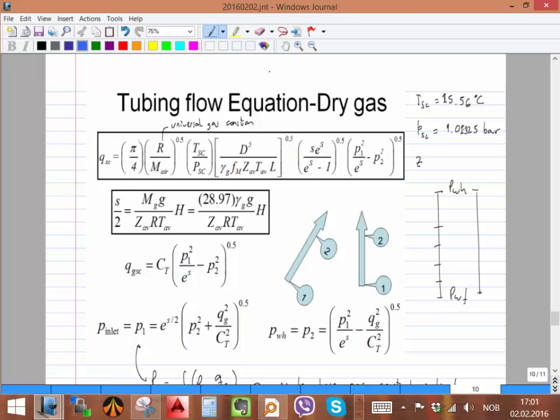And of course, then we're going to say what happens when there are changes with time. Okay, we're going to introduce some time changes, and we will do that not with a reservoir simulator, but with material balance. Just a simple tank model where we are taking material. Reservoir pressure is declining with time. We assume that the IPR doesn't change with time, and the only thing that you have to change in the equation is reservoir pressure. Okay.